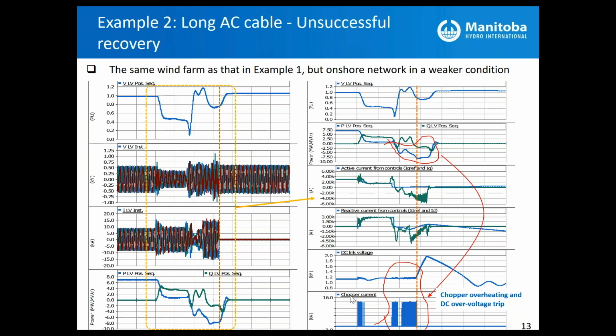Now, what can we do? You can provide that phase angle stability by, if we had conventional generators in the network and the network had been stronger, we would have had a chance to ride through the fault without tripping, like the previous slide.